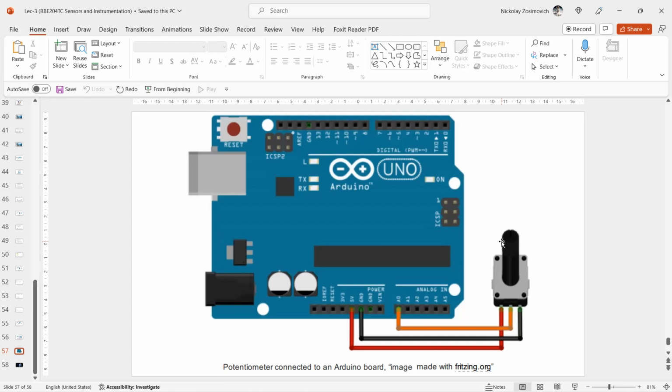When no other heavy loads are attached to the same source, this is a viable solution. In the default configuration, the ADC of the port has the supply voltage as a reference. And the input impedance is high enough compared to the sensor resistance to be neglected.